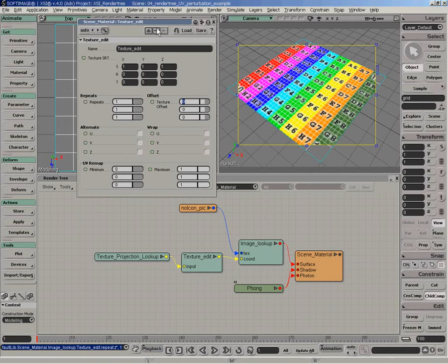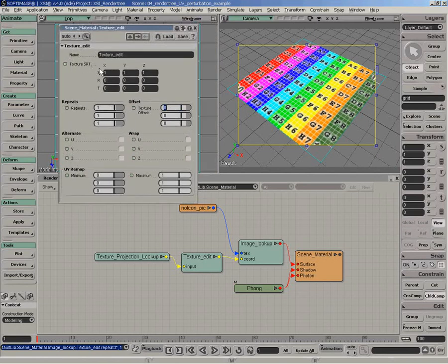The other control that is interesting is this texture SRT. Texture projections. There's really 2 types of texture projection. There's planar type, and then there's 3D type. The planar type is more like a planar projection, spherical, cylindrical, lollipop, where 3D projection types will be more like spatial texture projection, where the U, the V, and the W is being used. W being the depth in this case. So there's really 3 components.